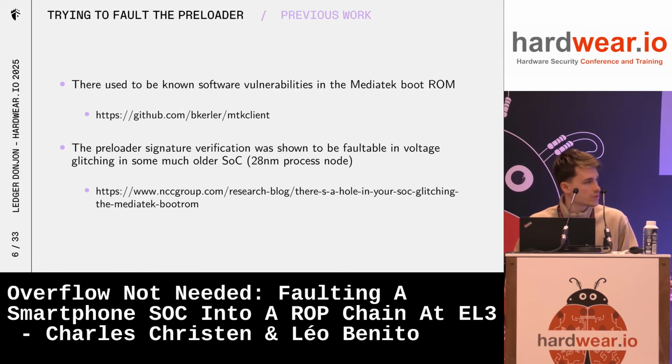Well, we are not the first ones to look into the security of MediaTek SOCs, and more specifically of the early boot stages. There is a great tool called MTK Client that gathers multiple vulnerabilities affecting the MediaTek boot ROM. But this is not applicable here, as these vulnerabilities have been patched on recent SOCs.